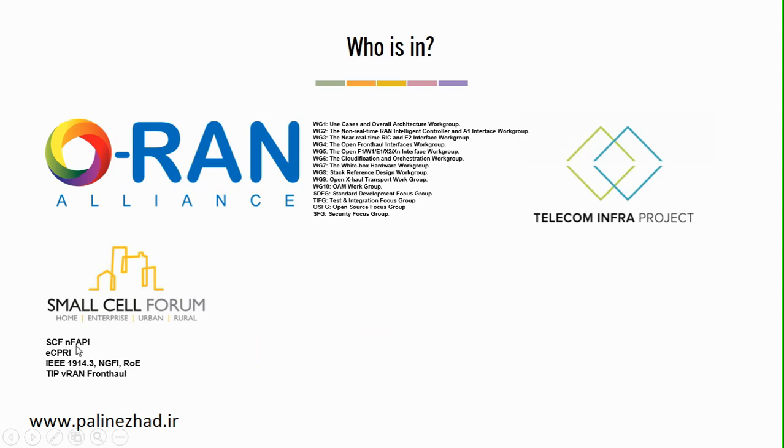There are different solutions for Fronthaul, such as SCF nFAPI, Network Function Application Programming Interface, eCPRI, Enhanced CPRI, Common Public Radio Interface, IEEE 1914.3, NGFI RoE.